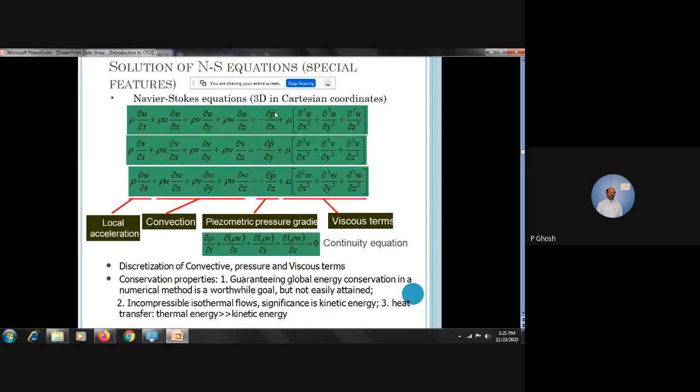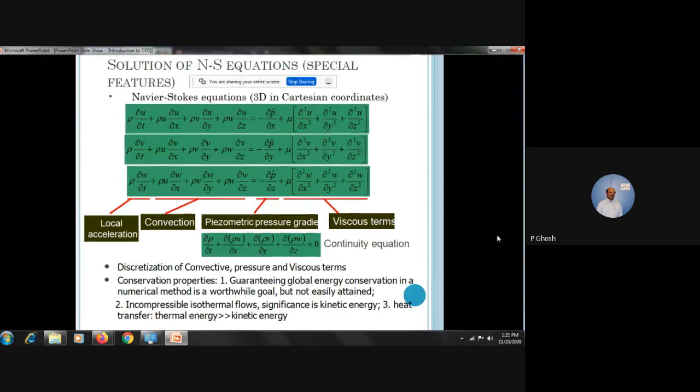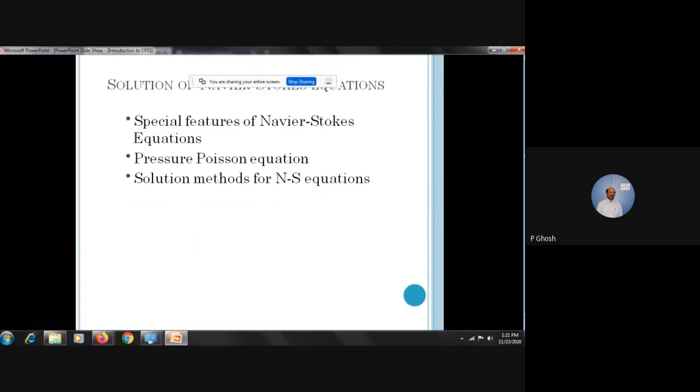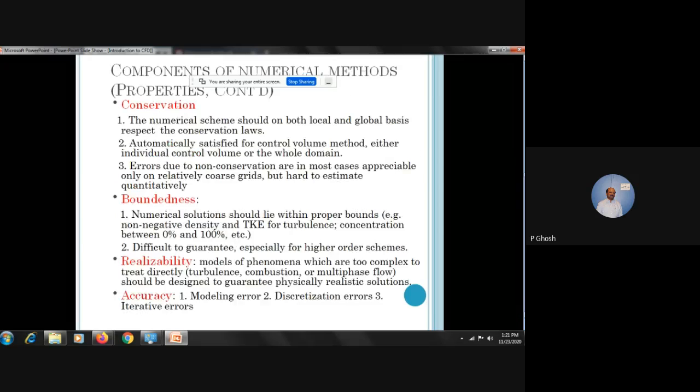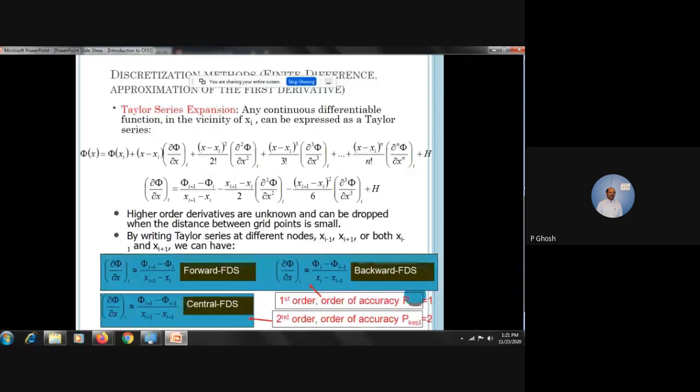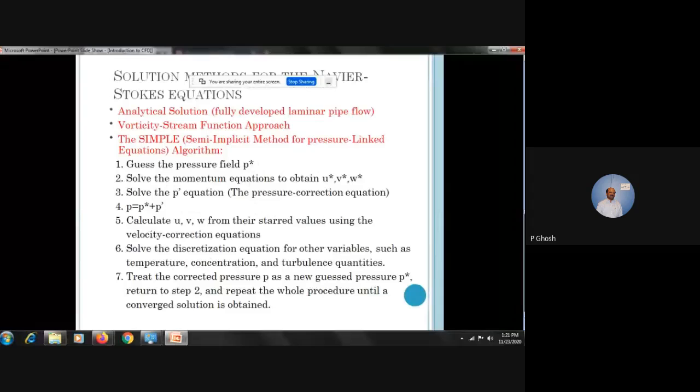So the pressure terms are going to be cancelled, because in both cases you are going to get del squared P by del x del y. So you will get only the velocity terms and viscous terms. That you can play around with, and that is generally what people do in most two-dimensional flow simulations. That is called the stream function or vorticity method.